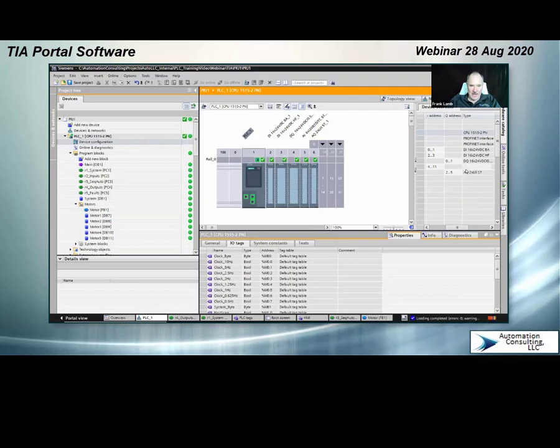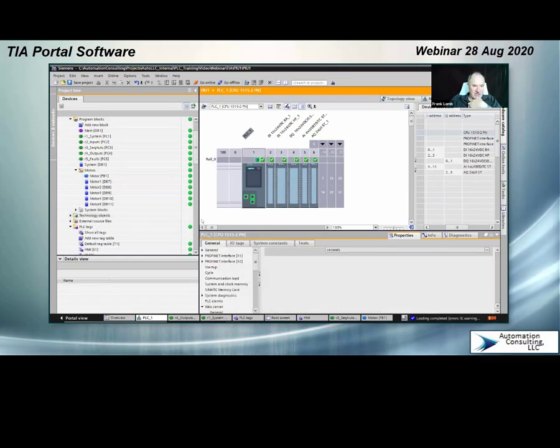It's a 4 analog input card, unlike step 7, where I would have had these up in the 200 plus kind of range, right? I would have maybe started at 256 or 800 or something like that. They automatically default. Same thing for my analog outputs. It used some other words here. Use the next available I and Q addresses. And it does much of that for the tags also. But that's pretty much it as far as hardware configuration.